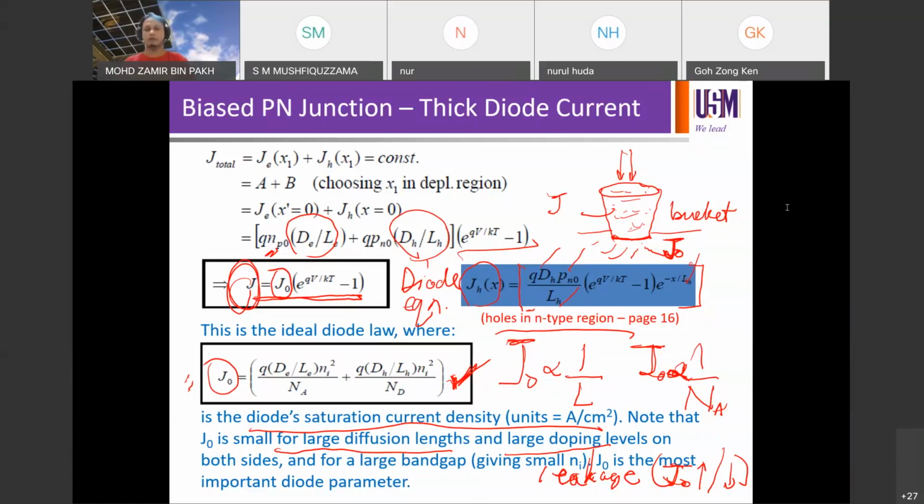Lattice scattering is more related to temperature. If you supply heat to the lattice and the material, the lattice vibrates, and you get enhanced lattice scattering. But if you put more dopants in the lattice, it's going to be more impurity scattering, assuming no change in temperature. Okay, what else? What is the other but?